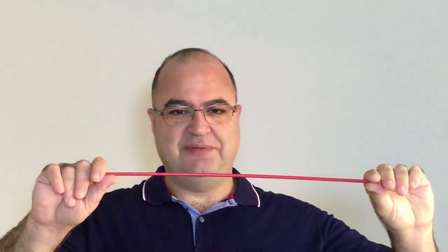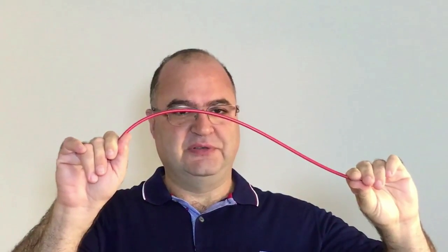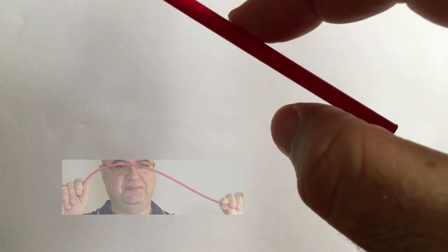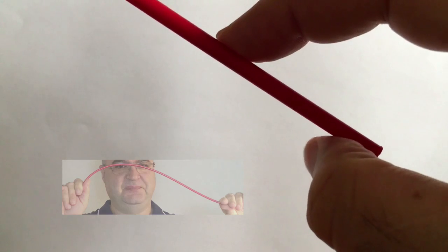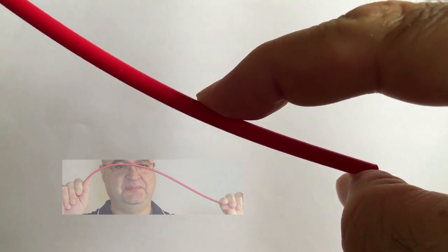The next configuration is a beam with a moment applied at one end, and the other end is neither fixed nor free to rotate freely, but somewhere in between. This is how it deforms. At the resisting end, I start with a simply supported configuration. That is, I just apply a finger down on the right side and gradually apply a resisting moment, but not enough to make it tangent to the horizontal.